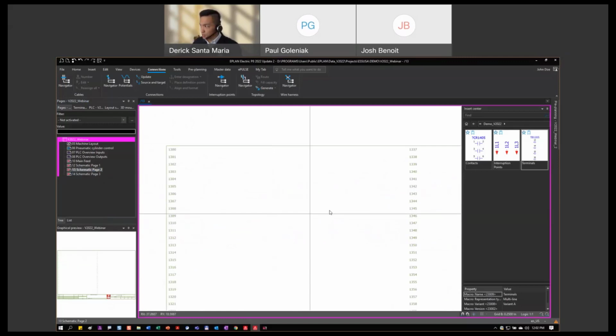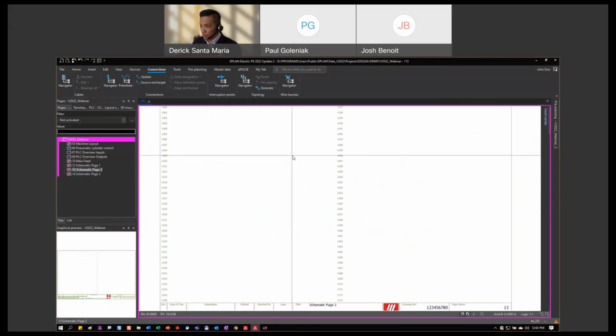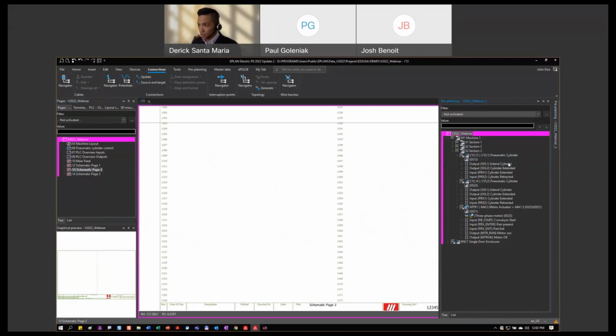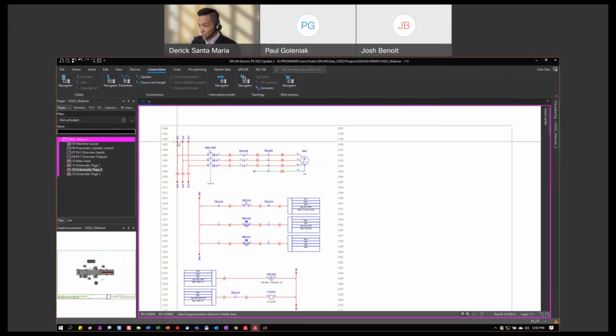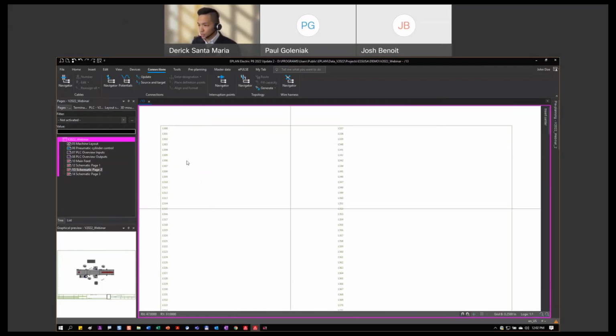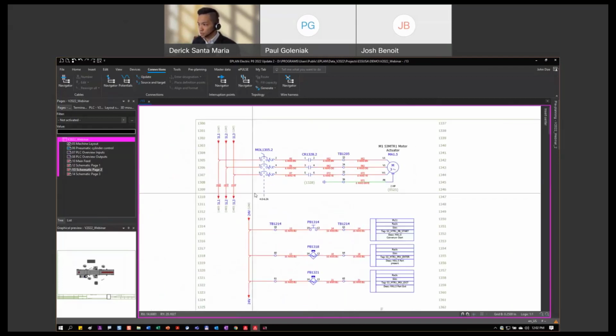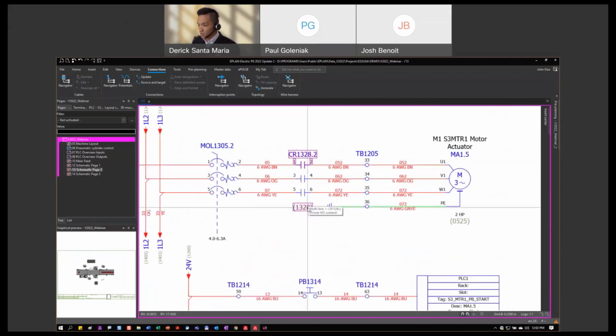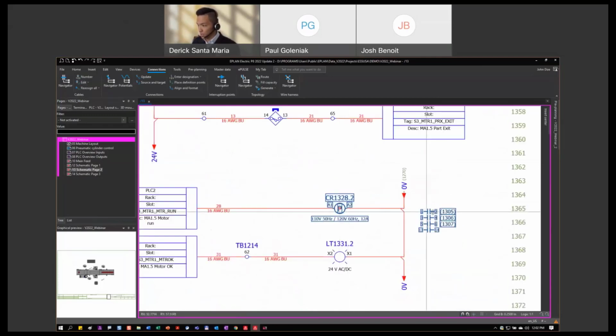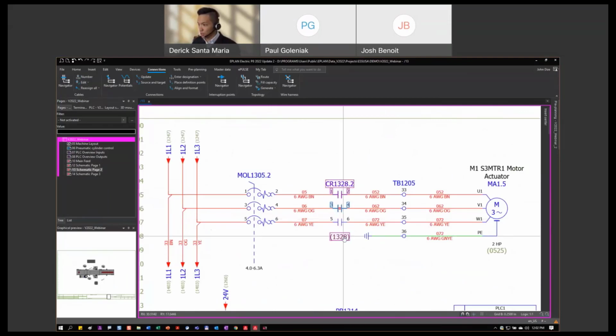I'm gonna go ahead and complete my project using my standardized and pre-built macros or blocks within EPLAN. For example, this motor macro. I've created it so that I can always use it for future reference. For example, this motor, I've already configured the contacts. These contacts always cross-reference to the main function, which is the coil, and I can simply jump back and forth between those two.